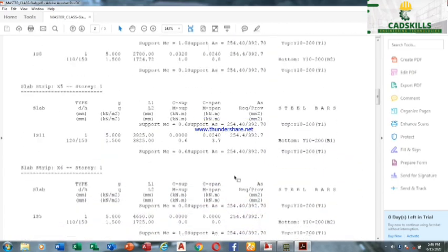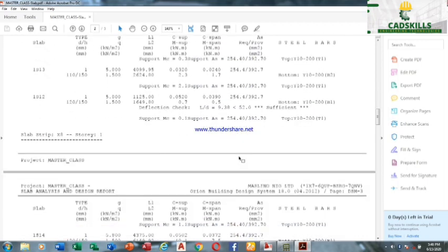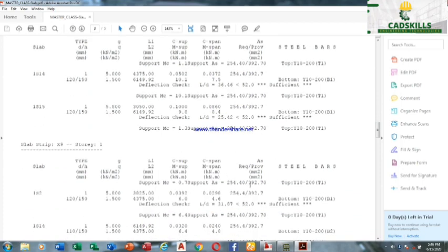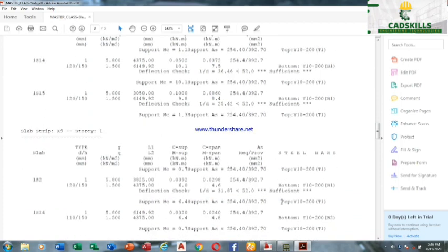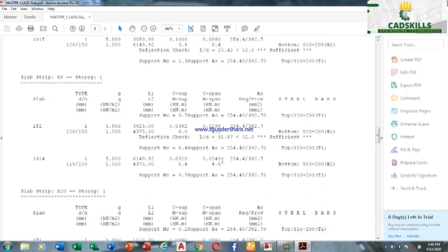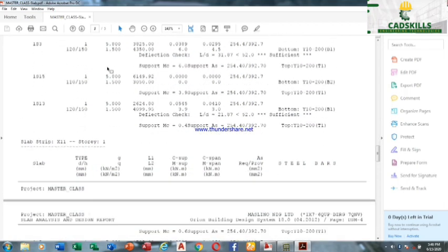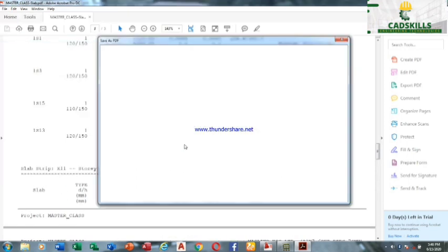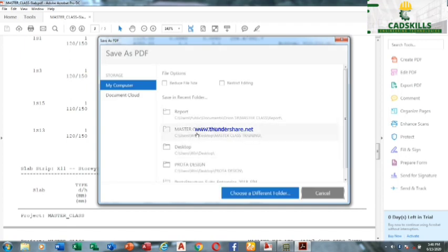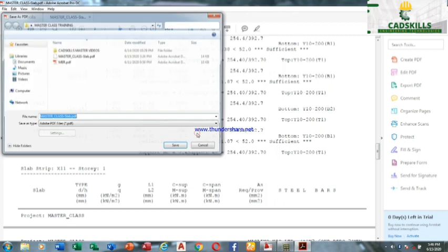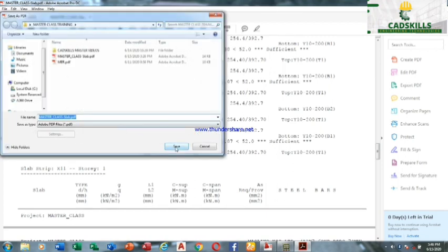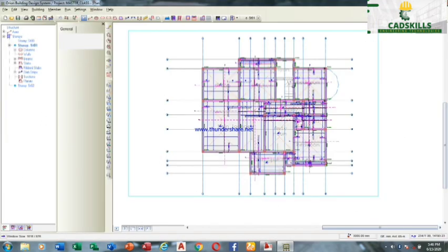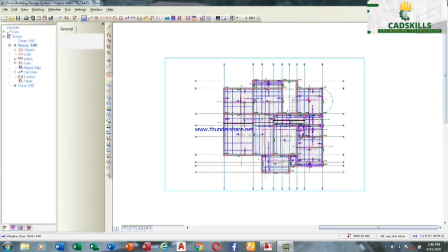So we use Y10. So many people have been using too much reinforcement for their work. That is waste of money. When Y10 can actually do the work, there isn't need for Y12, and you know the amount difference on it. So this thing you have to change, save it. Save it. So close. Now we are ready to run analysis.